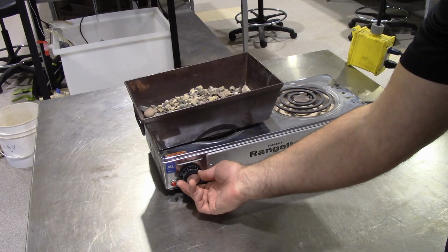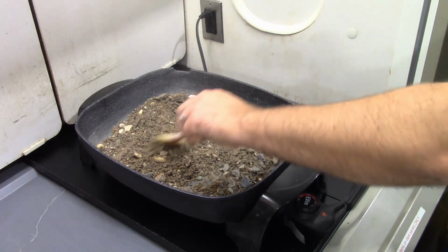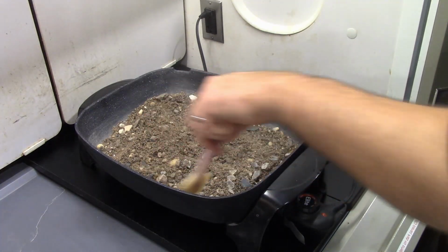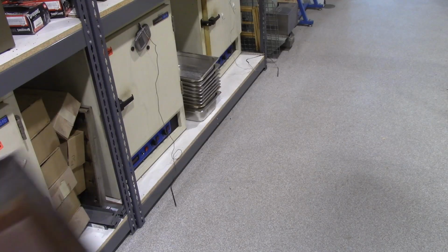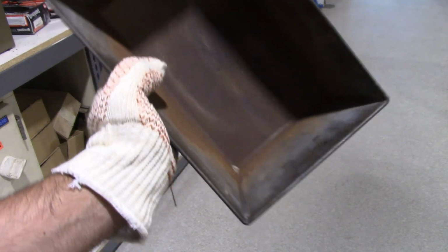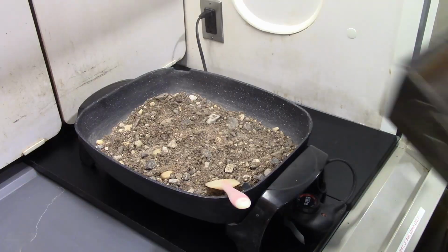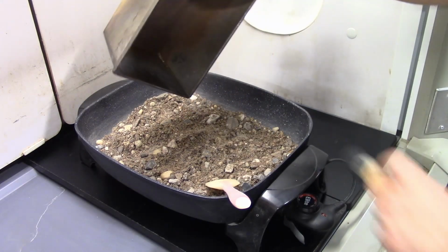A gas or electric range is also allowed to dry the sample pan. The heat should not cause the water to excessively boil and spray the material out of the pan. The sample should be monitored to ensure that no excess particles are sprayed outside the container. If after drying loose particles are observed, these should be incorporated back into the sample.